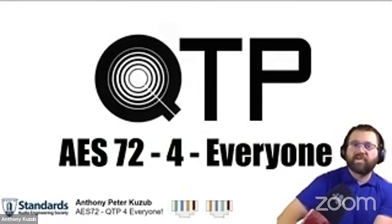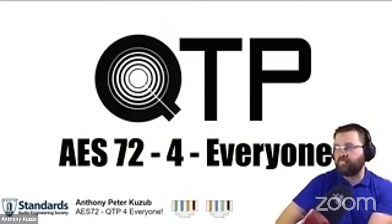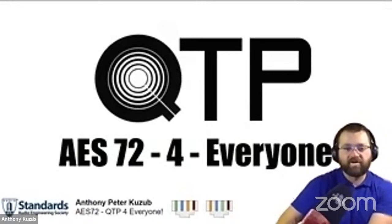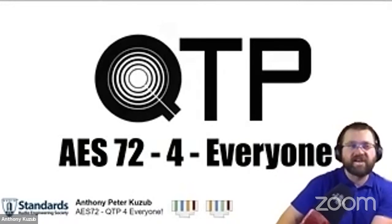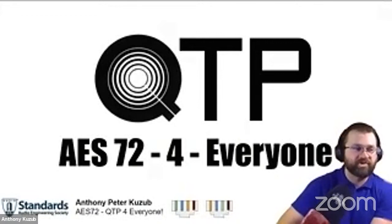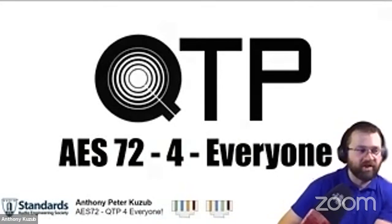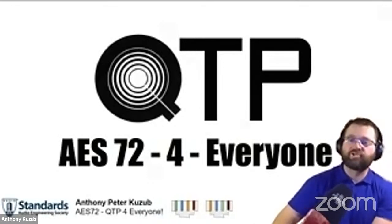For me, I am not one who recommends using this as a microphone snake over UTP. I'm one to say, if you want to use a microphone, you have to use an STP cable for your shield. But then you also have to follow the other rules, which are, well, it has to be bonded to the shield enclosure in the proper ways.